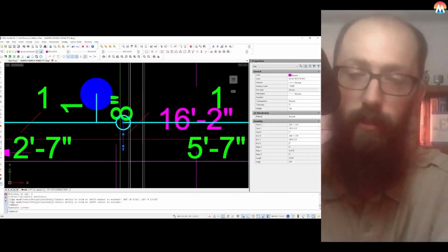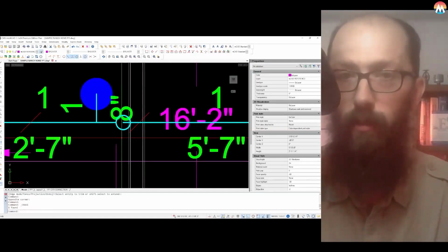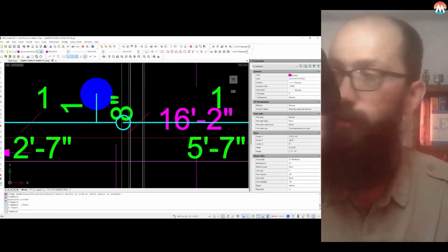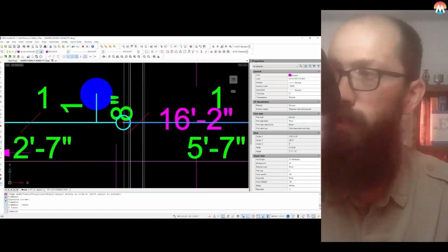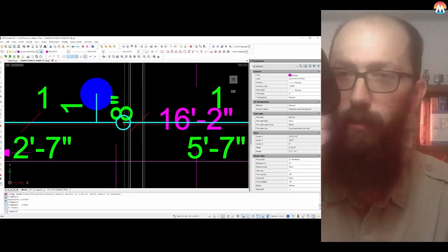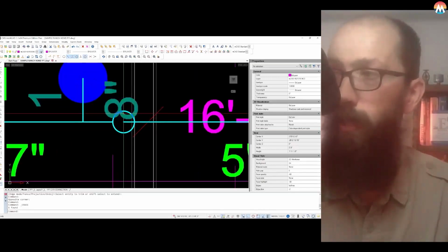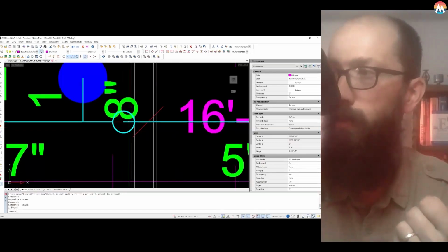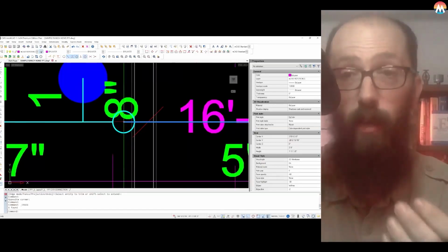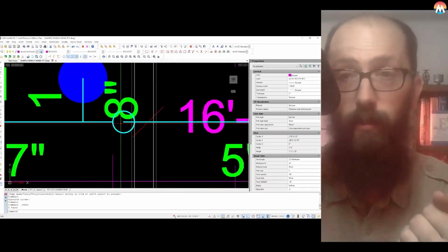is that is the ideal way to show it, but our symbol is a little bit too small and our lines are too thick, and so when we print to paper, what you see here is it just kind of looks like a filled circle almost. And so by showing it this way, if we had a bigger circle, what that would represent is that this pipe coming from the right hand side is at the top of this riser nipple, and this pipe going off to the left is coming out of the bottom.